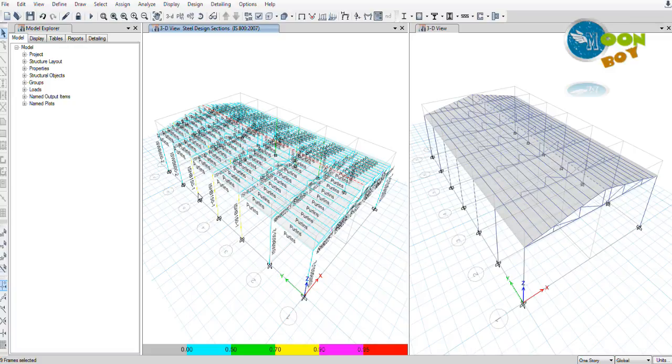If the design from the program is not coming safe, then you have to do this step. Otherwise it is not required if you are taking less loads or a different design or different truss. So based on my truss, I have got these failed columns in the red zone. At the time I analyzed and designed for the first time, then I iterated several times and made the other columns safe, and at last I had to change the point bracings for these three columns because they were not coming safe. They were in the red zone, now they are in the yellow zone, as you can see now.